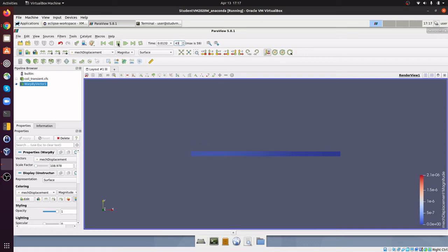And since we're using an axisymmetric setup, the rotation axis here, the inner vertical line here, is always oriented exactly in y direction. So it will not rotate around the z-axis and will not move in x-direction, since this would violate the axisymmetrical boundary condition or modeling strategy. Okay, so this is the mechanical deformation.